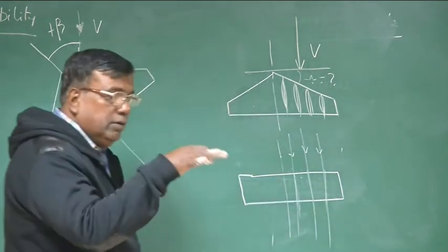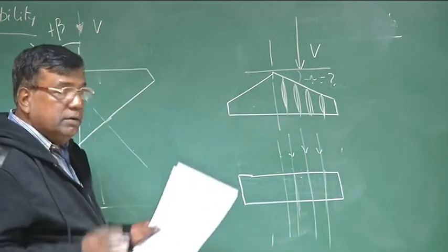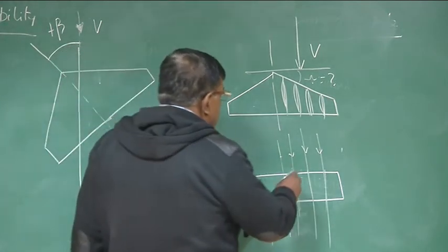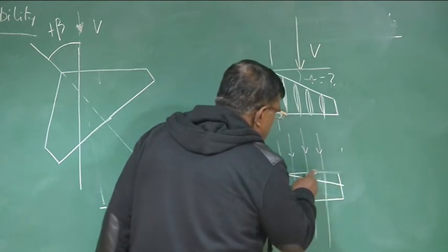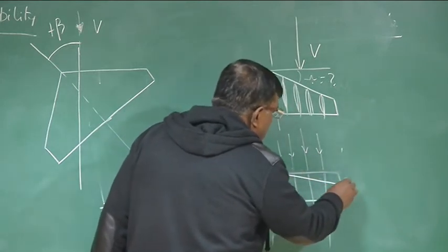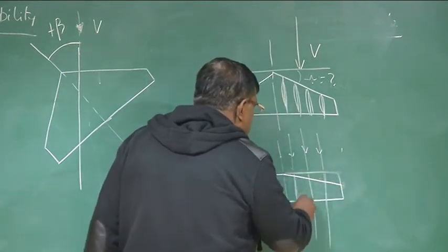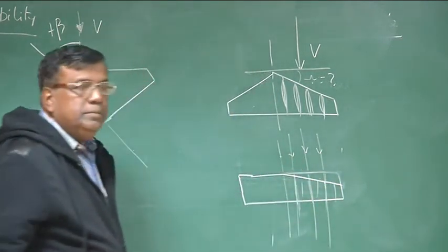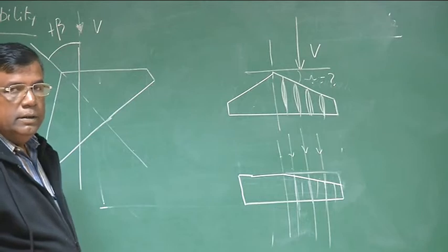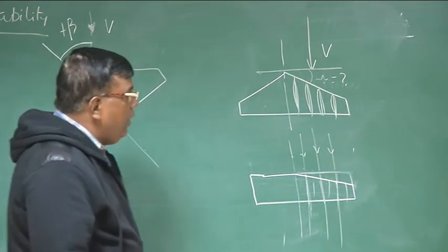The normal component to the leading edge decides the majority of the forces. So if I give a shape like this and the aerofoils are still kept like this, then the normal component is the same. There is no change in the normal component. So what advantage am I getting? What is our aim for a sweep?